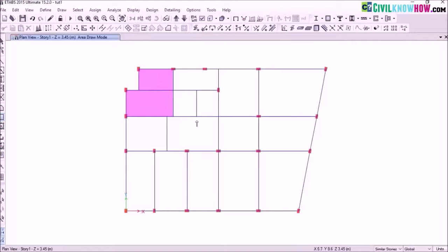but there is an alternate method which is much more effective actually, and you can save a lot of time too. That is, I'm going to select the slab from here to here. So over these 3 sections actually I have assigned a single slab. By adopting this method, I can save a lot of time. That is, I'm going to select the slab and the frames. So I need to split my slab between these 2 frames.